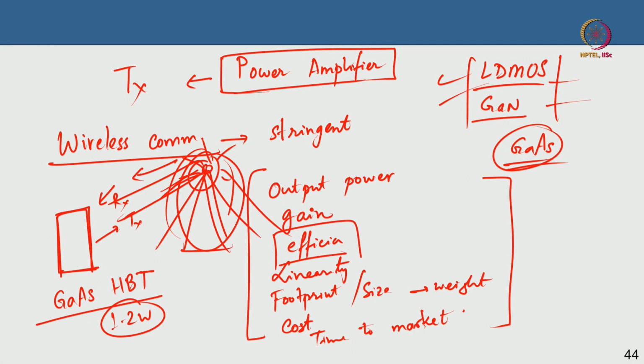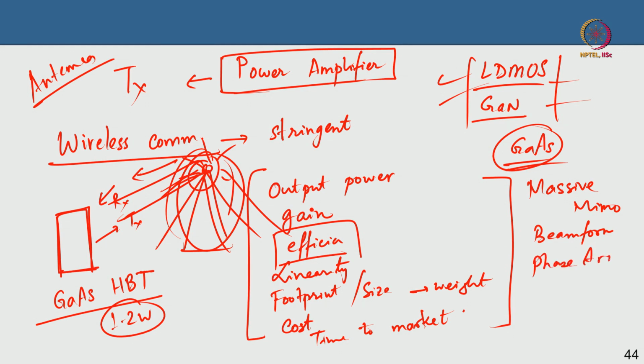We call it cellular infrastructure application. And more and more improvisation is done in the transmission itself in terms of the antenna design. There are concepts that you might have heard about, things like massive MIMO, and then beam forming and phased array. Although phased array radars have been popular for a long time, in cellular civilian applications like a cell phone base station, people are now adopting phased array beam forming, where you do not want to isotropically emit the signal everywhere, because it is a waste.